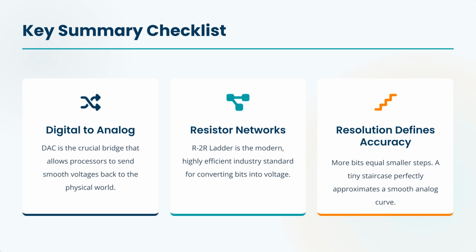To conclude, the DAC is the crucial digital to analog bridge. The R2R ladder is the highly efficient industry standard for resistor networks, and the resolution, defined by the number of bits, determines the accuracy of the smooth analog curve approximation.